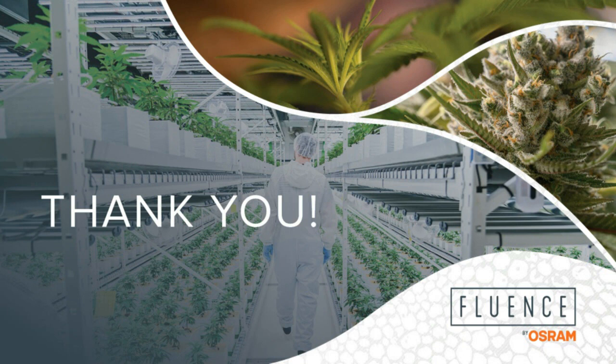Well, in the case of VPD, you want both, right? You want to understand what the air temperature of your environment is, and you want to also understand what the leaf temperature is, because they're going to be different under different lighting sources. As I explained with the whole infrared and radiant heat, with HPS, we don't have that in LEDs. So what growers can do is to combat that with raising the air temperature in the room, which will thus elevate the leaf surface temperature. And they can use an infrared thermometer gun to check that to make sure that they're within the optimal ranges.